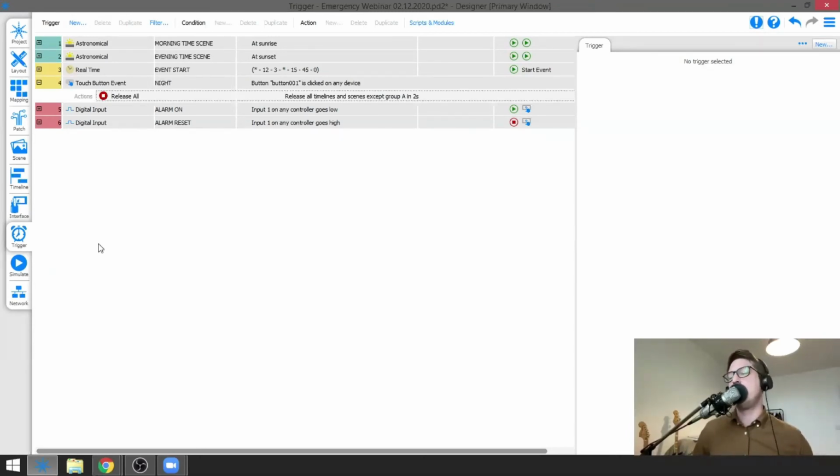Typically speaking, we can do integration with lots of different things, such as UPSs as well. A lot of UPSs now have smart features where we can send a command over a serial connection or a network, and that can then control the power. But as I said, if you want to do it straight from Pharos, then you need to be wary that you can do it with a Rio output, but it needs to be under 48 volts.